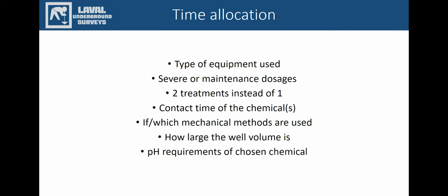The well volume is important because this aids in the dosing requirements. How often do your customers not know how deep their well is? If this information is unknown, it's important to retrieve it because you don't want to underdose or overdose the well. Overdosing can have hazardous implications, and underdosing will leave the customer and you upset and frustrated, since a second or alternate treatment will need to be done.